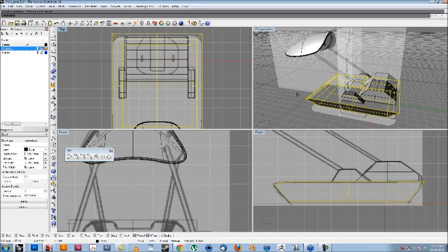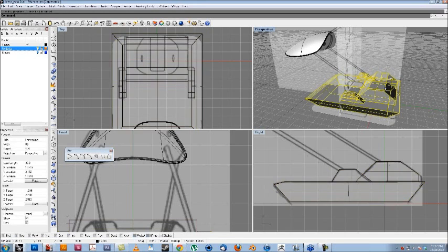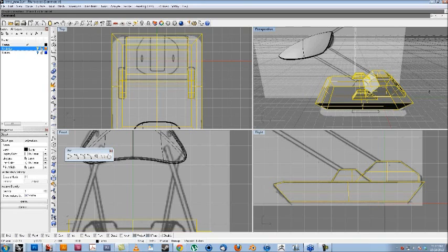So it's like, okay, I built my curve and then I extruded it out, then I tapered it. Now I'm going to join all these parts together by Booleaning them together so they're one solid shape. And then I'm going to start worrying about my fillets.